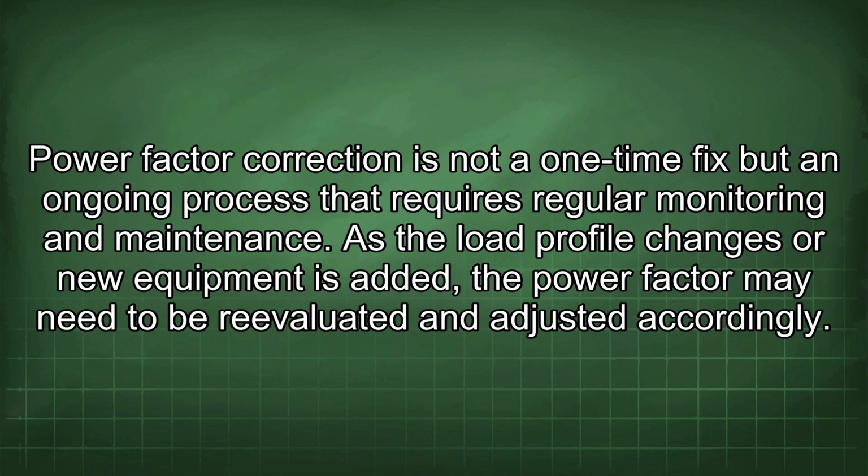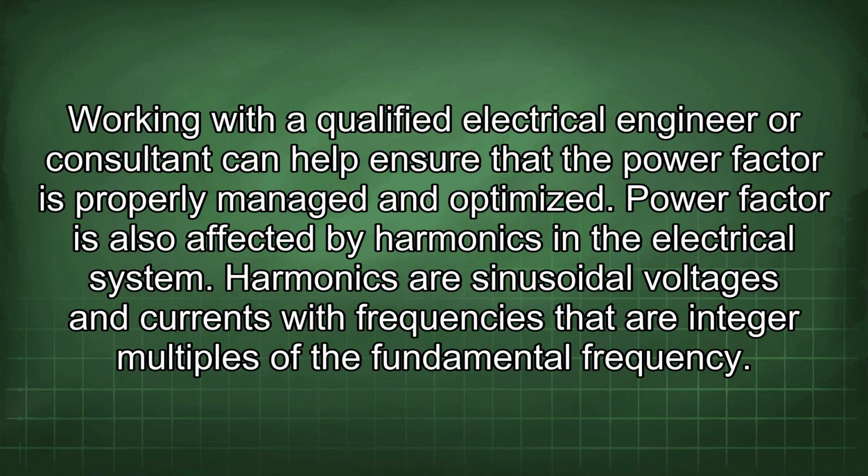Power factor correction is not a one-time fix, but an ongoing process that requires regular monitoring and maintenance. As the load profile changes or new equipment is added, the power factor may need to be re-evaluated and adjusted accordingly. Working with a qualified electrical engineer or consultant can help ensure that the power factor is properly managed and optimized. Power factor is also affected by harmonics in the electrical system.